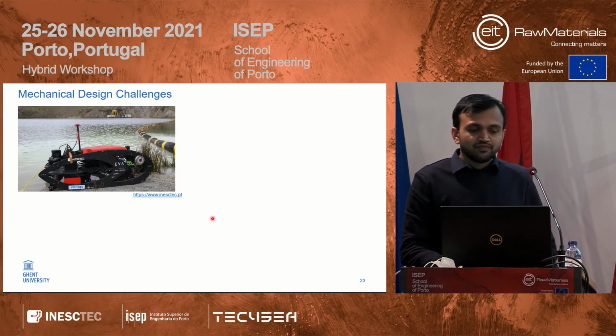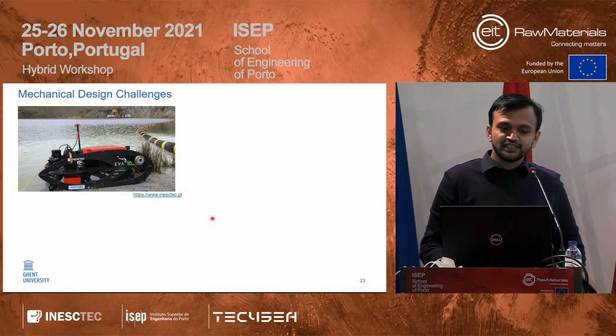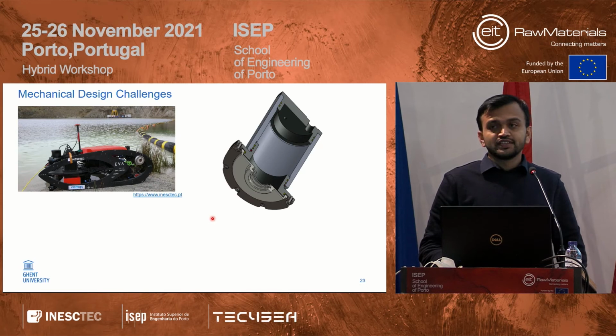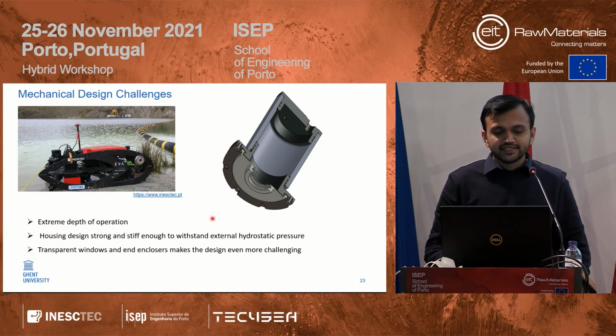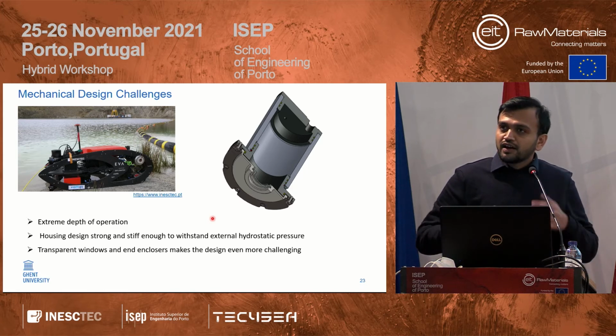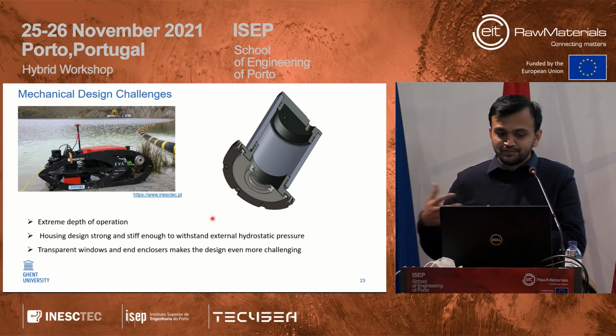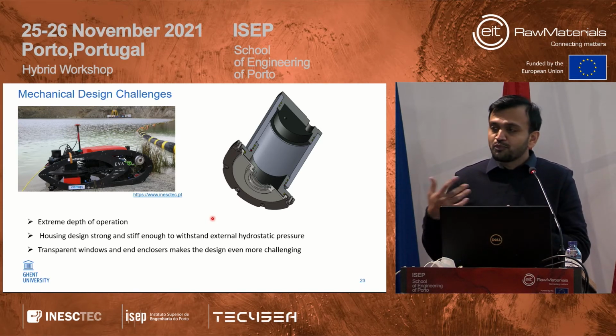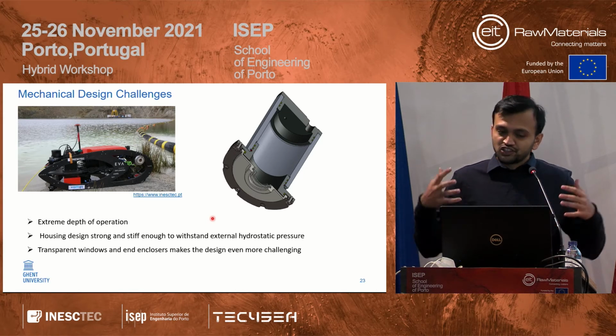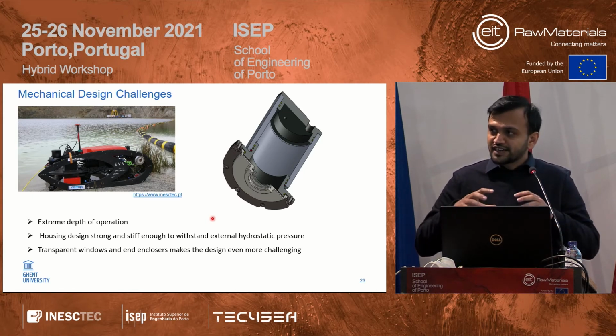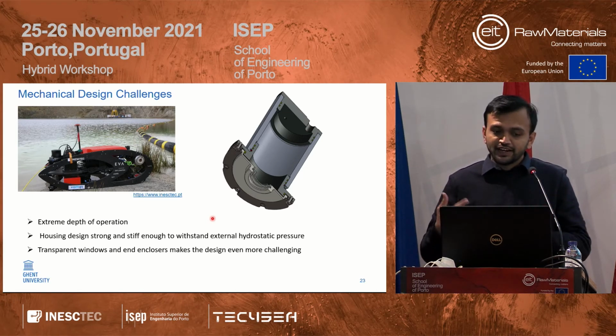In this project, we are responsible for mechanical housing design. And what are the challenges we currently face? You can see here one example of a mechanical housing. In this case, geologists or mining companies want to go as deep as possible. Extreme deep operation creates a huge pressure on the housings that will try to buckle and fail the mechanical components.